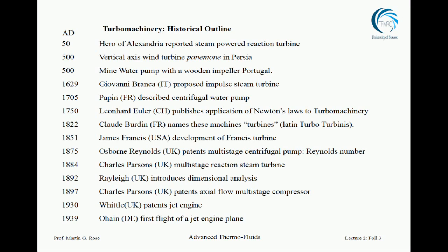Yeah, the process is dimensional analysis. So we are analysing things from the viewpoint of what dimensions are present in the numbers. The end result are dimensionless groups. And these are numbers which, as the name suggests, have no units. And their power is that they have no units. It makes them applicable across a huge range, and that's something to be understood. But everyone, including Monty, do ask questions as soon as they come to mind. It will help us all make progress.